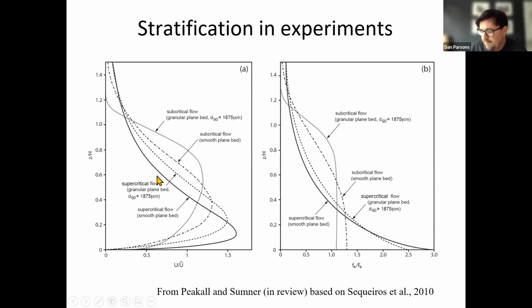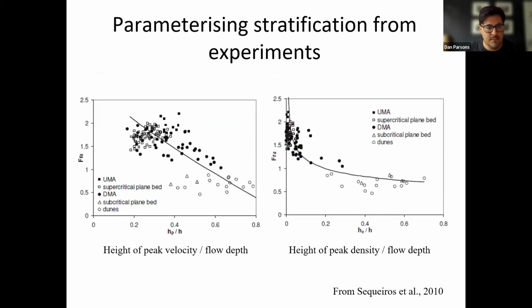So more stratified flows with higher velocities down near the bed, and of course that then means different types of forces, different types of positions of the velocity maximum. Means you either get reversal of that secondary flow cell in a bend, or a flow normal like a terrestrial river flow. And that's really important in then controlling where these sediments move to.